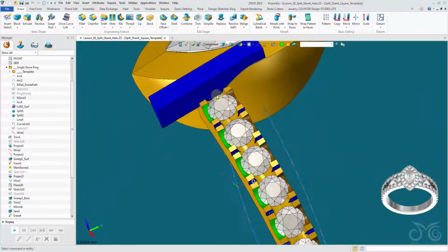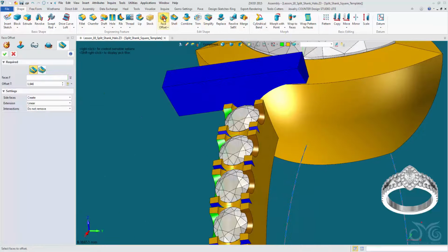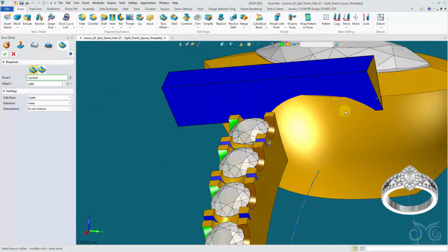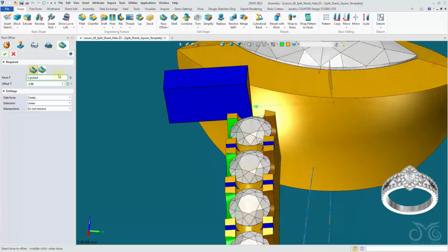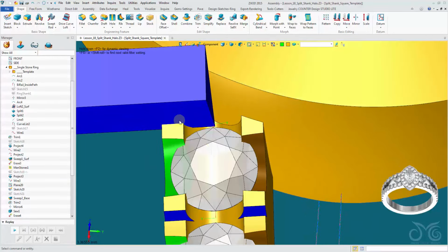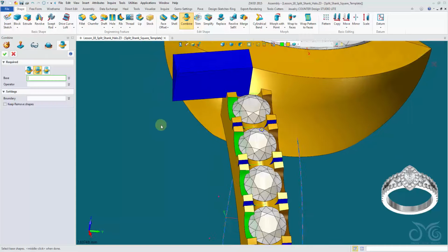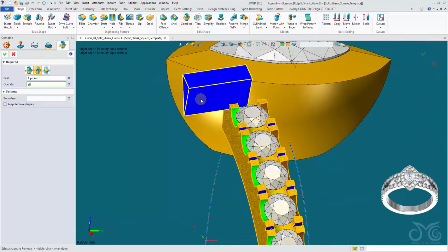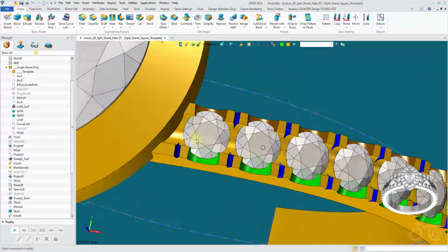Okay, and finally for this V cutter here, I'm going to face offset, bring it in to here, and now I can combine and remove, okay, because I wanted to cut only on this side since we have no material there. Combine, remove again, and there is the single cut.